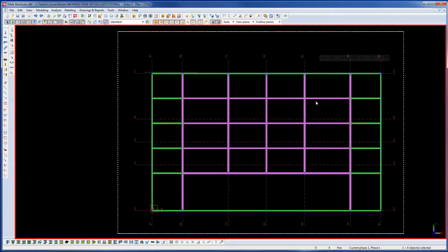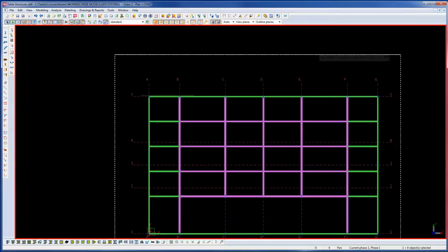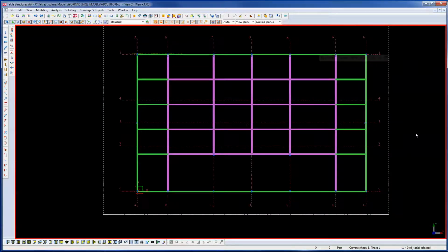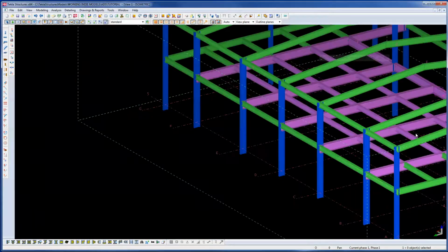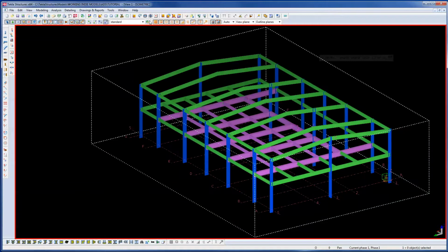Okay. Just do a Control Tab. Just flip through these open views. Okay. Create a clip plane. What's that do? It basically does what it says on the tin. You can create 6 clip planes if you can visualize a dice, the 6 sides of a cube.